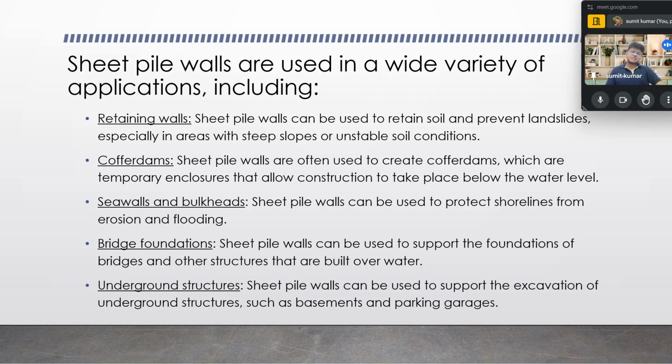Now the next one is the bridge foundation. So sheet pile walls can be used to support the foundation of the bridge and other structures that are built over the water, that I have already said. Apart from that, for underground structures, the sheet pile walls can be used to support the excavation of the underground structure, such as the basement or parking and garage.